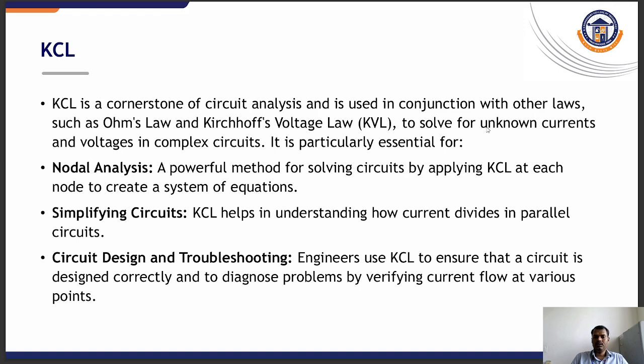It is a powerful method for solving circuits by applying KCL at each node to create a system of equations. KCL helps in understanding how current divides in parallel circuits. We can also use KCL to check whether a circuit is designed properly, and we are able to diagnose problems by verifying the flow of current at various points.